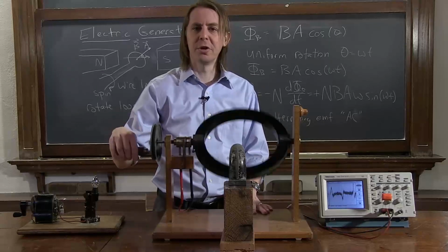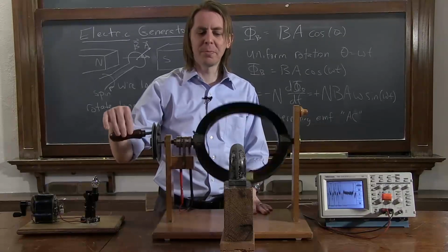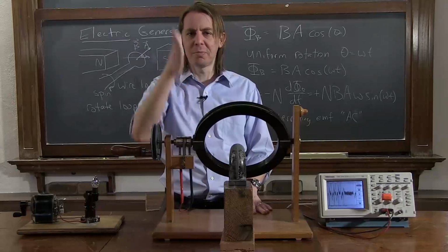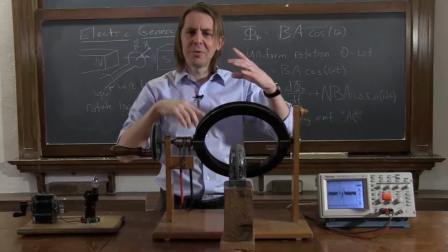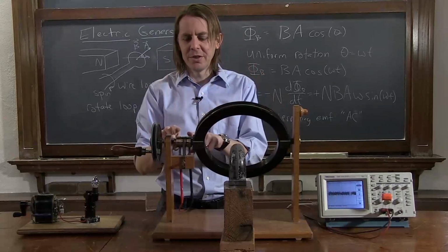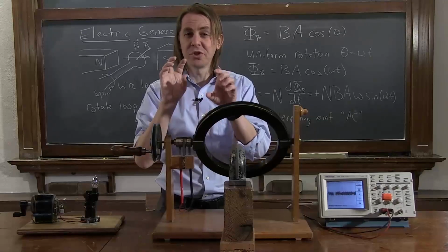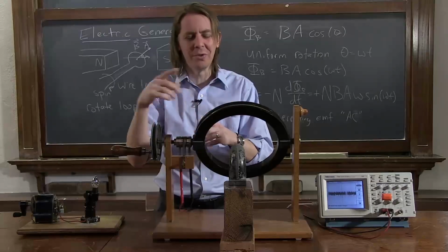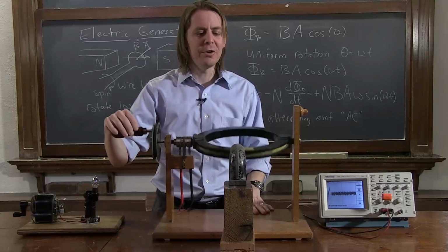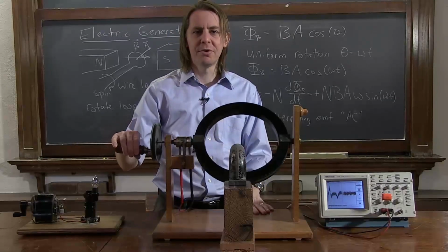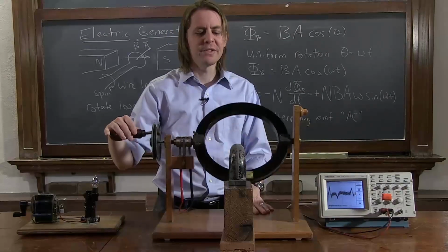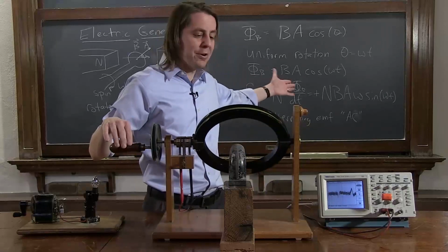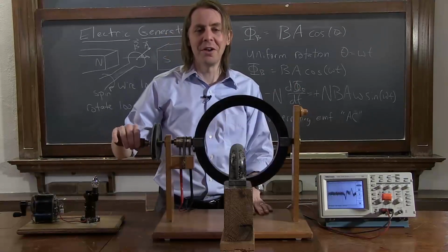If I spin it faster, you'll get a bigger effect. It'll come together more. You're seeing really sharp spikes. That's because when something is spinning, and then you have to have electrodes on it, there always has to be some contact. There always have to be these brushes for this kind of a setup, and those lead to those spikes. So don't worry about the spikes. But there you can clearly see the EMF forming that we've been talking about. And you can see it's not a perfect sinusoid as we describe here, but that's because this setup is not ideal. Okay?